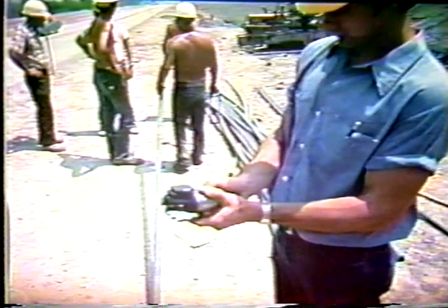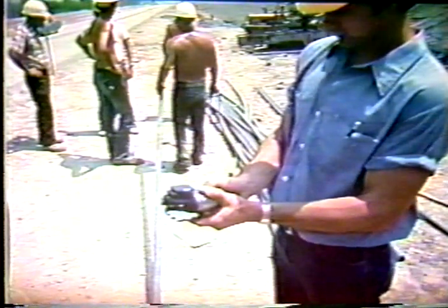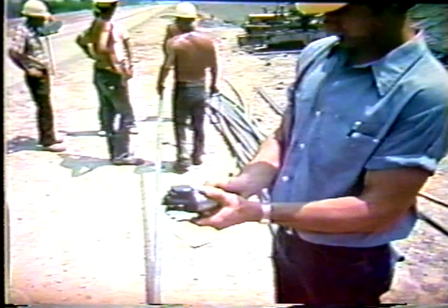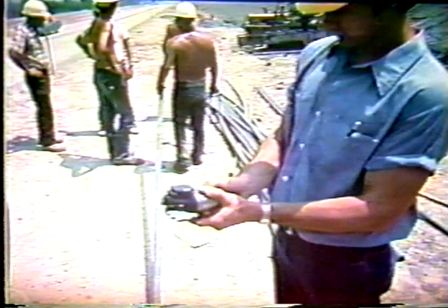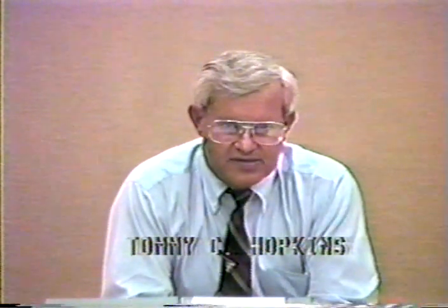Now, the pipe is either slotted or perforated. Generally, what's being used today when you're installing horizontal drains is a plastic slotted pipe. And for different types of soils, the slots have different widths and so on. I guess California sort of pioneered horizontal drains. They've got so many problems and so many landslides there. They pioneered this technique, and originally they used metal pipe. So they have a lot of old installations there that have been in for several years and have worked very effectively.